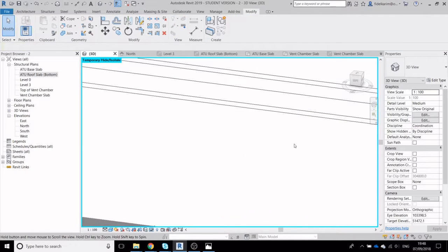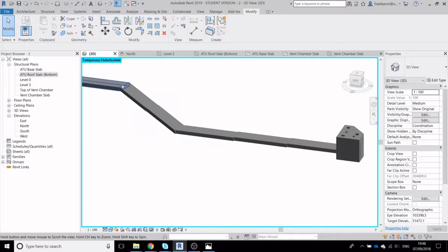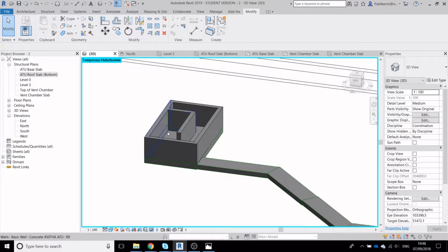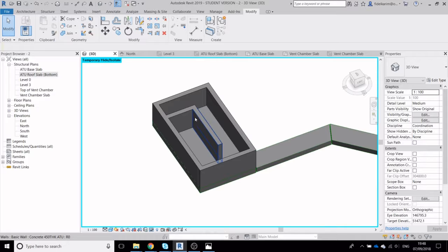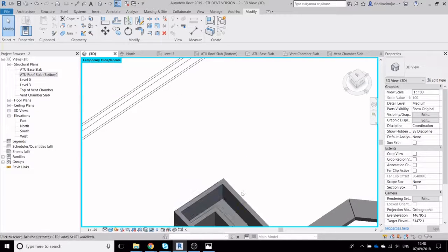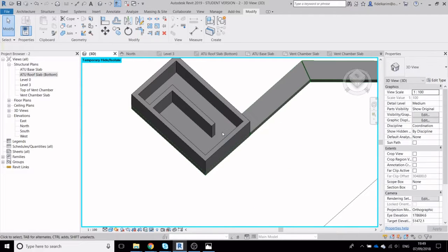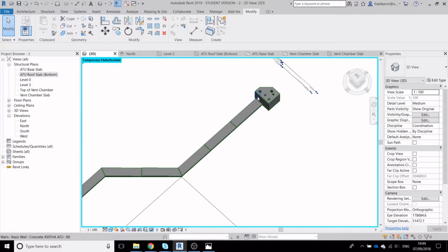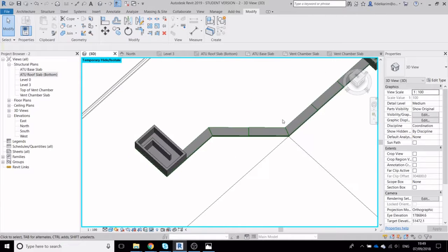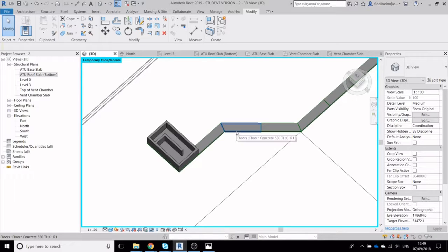And we're going to put the 2 vents in here. And we're going to put a sloped floor on top of this. So it's called benching. Basically, we need the water condensation to flow down into one point on this side, and then we need it to flow down onto one point on that side, and that will go into an external drainage system. And we'll have another one there, which will go back down the pipe. So I'll see you on the next video.